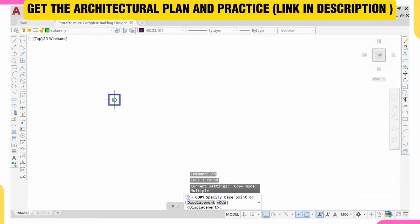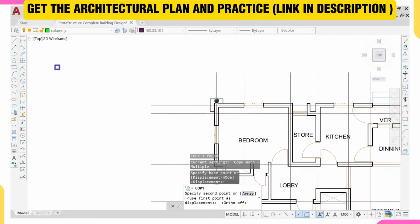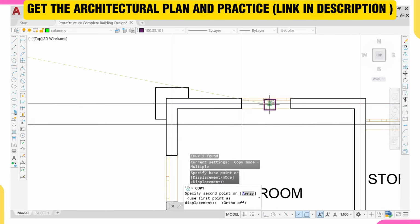If you are placing your columns, make sure you place them anywhere you're having wall intersection, or make sure you place them at any point you're having wall intersection, and make sure that your column is inside your block wall. For example, don't place a column in any of your windows.